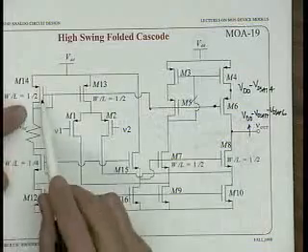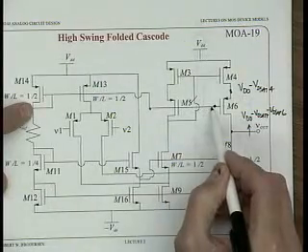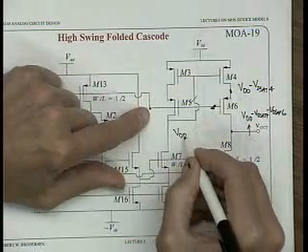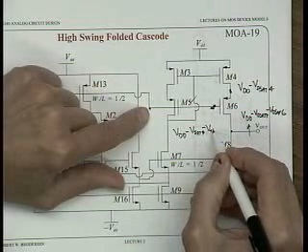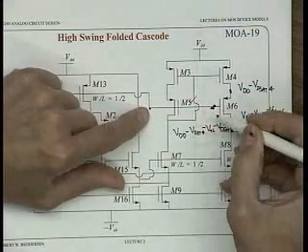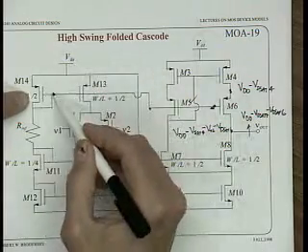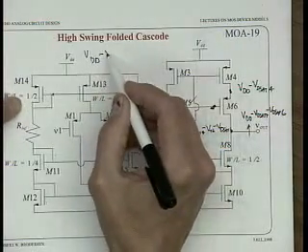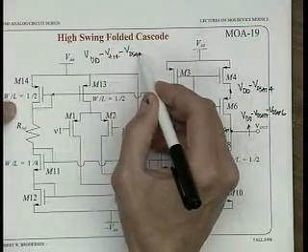And so what you have to do is look, and what sets this voltage right here is actually the voltage on this gate. So this gate voltage here needs to be VDD minus VDSAT of 4 minus VT of 6 minus VDSAT of 6. Okay? So that's what I have to have this equal to, right? And what is this voltage equal to? Well, let's see. This is going to be VDD minus VT of 14 minus VDSAT of 14.